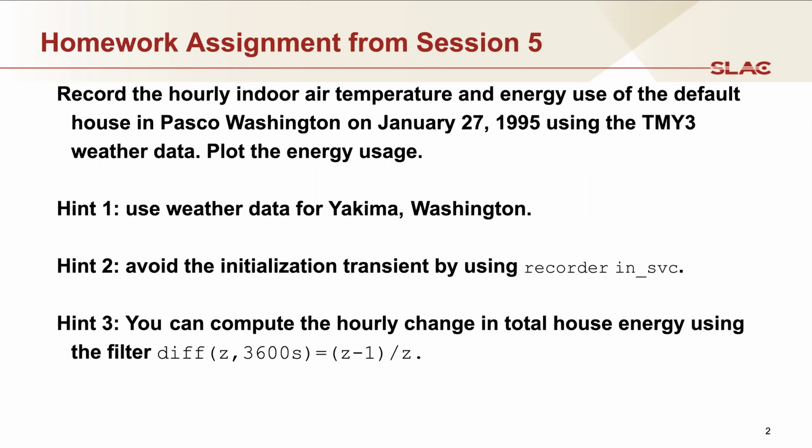Another hint that I provided was that because of initialization transients, which is something that we talked about previously, it's a good idea to start the recording later than the start of the simulation itself. So if we want to start the recording and collect data on January 27th, it's a good idea to start the simulation a few days earlier, and then use the in-service property of the recorder to enable the recording on the day that we actually want to record.